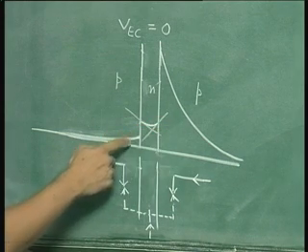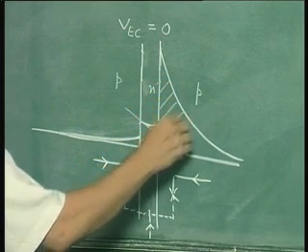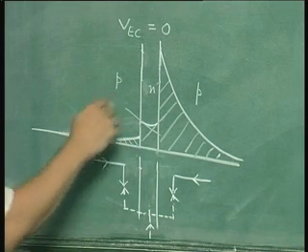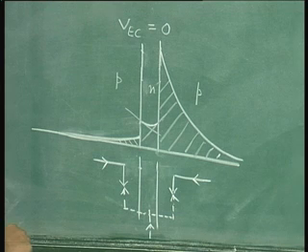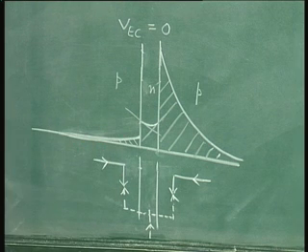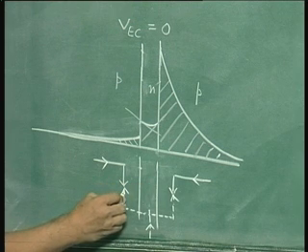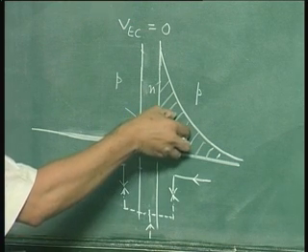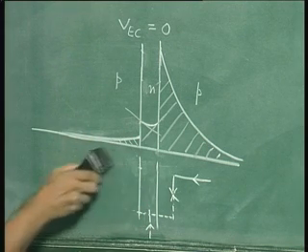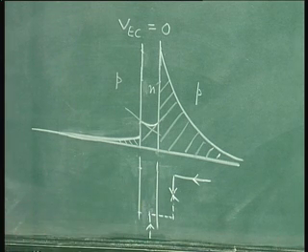Now from this diagram you can very clearly see that the excess carrier concentration in the collector is much more than the excess carrier concentration in the emitter because of the difference in the doping levels, and because the forward bias across this junction is the same as the forward bias across this junction here, the emitter junction. So therefore this current will be much more than this current, okay, because the amount recombining here would be much more than the amount recombining here. Therefore we could even remove this picture and we are left with just this picture. Now this is very easy to understand.